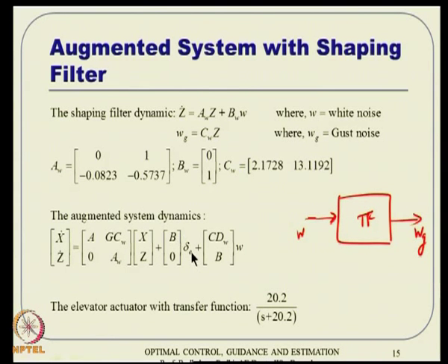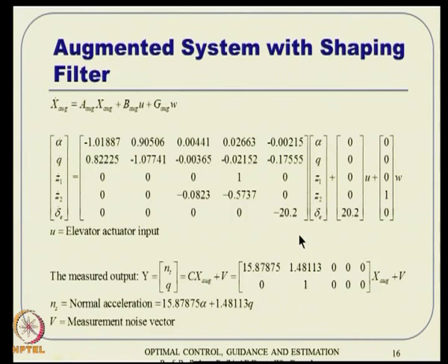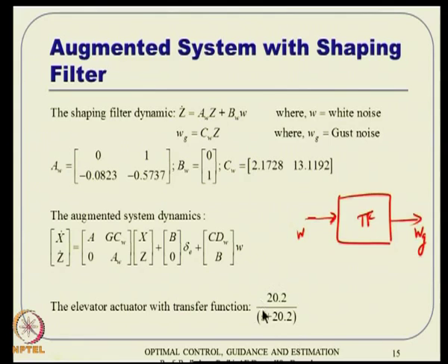And also, after getting this delta E, it has also passed through some sort of actuator dynamics, and for control, this elevator deflection is a first order system with this transfer function. All right, so this is what it is. Then ultimately, this realization can be done separately or together. There are both ways of doing that, and if you do hard coupling, that also will come into the picture. This can be realized as a first order state space equation.